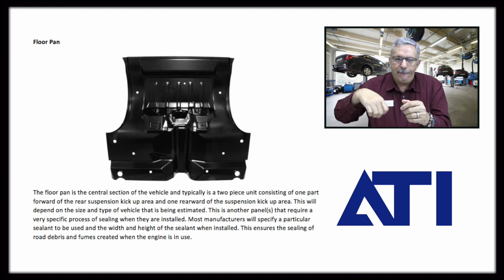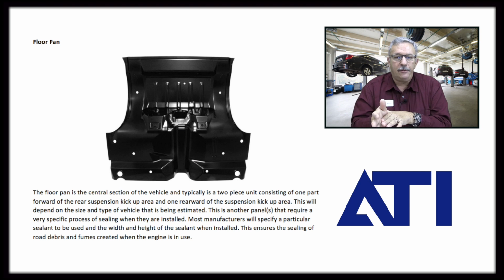And I'm not talking about putting plastic on it and sanding it down and sculpting it so it looks right. I'm talking about a hammer and a dolly, a slapping spoon, you know, anything that's required to move the structure back to its pre-loss position. So it's not only the shape, but it's the state of the metal that we've got. It's two things we're looking at here, the shape and the state.